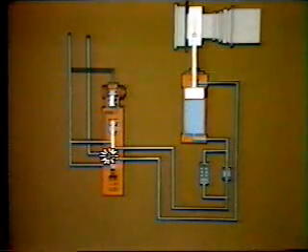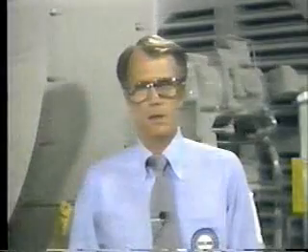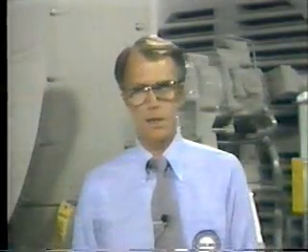At 90% engine speed, the electrical impulse is removed from the solenoid, allowing the solenoid to extend. The spool shuttles and oil flows into the top port of the actuator, forcing the piston down. Oil flows out of the bottom port through the check valve to the oil tank. As the piston recedes, the vanes move to the minimum open position. This final movement is completed quickly to avert engine stall during shutdown.